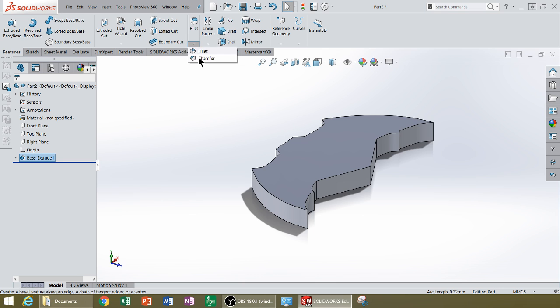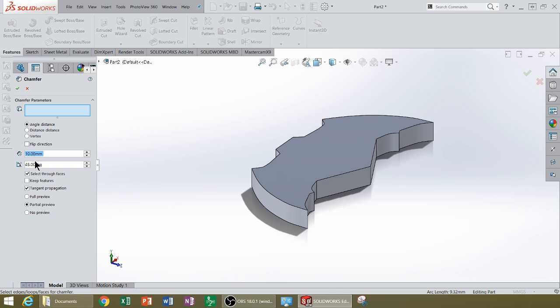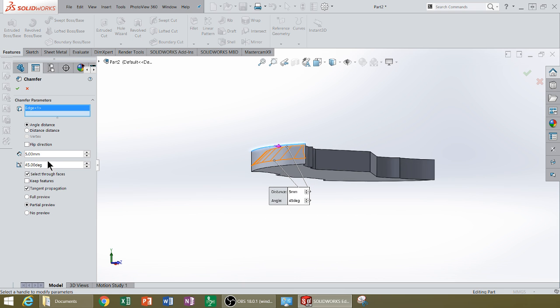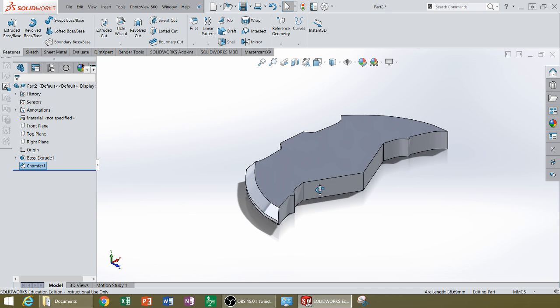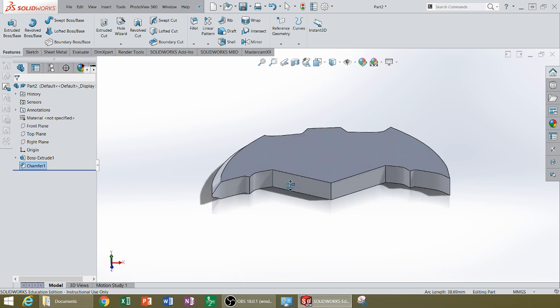So as an example, perhaps put a chamfer. And I'll make it a 5 millimeter chamfer on this edge. It's a little steep, so let me make it about a 3 millimeter. And a 3 millimeter. Top and the bottom, let's take a look at how that looks. And now I've got that edge, that Batman-like edge.